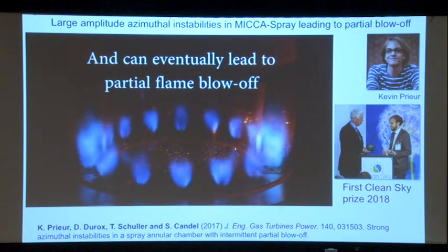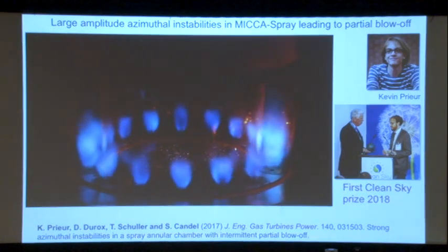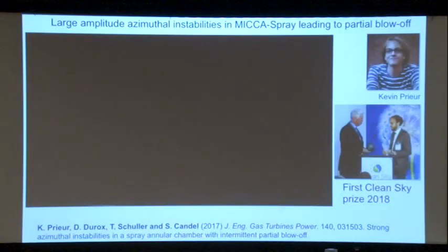The frequency also changes, and suddenly some flames are extinguished. You briefly saw that. When the pressure fluctuation becomes sufficiently large, you get extinction. You get a few flames which are extinguished. The flames that are extinguished,